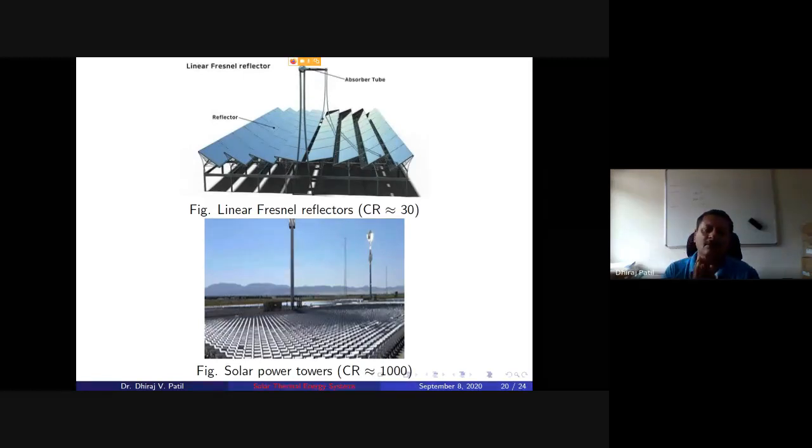So if I have 10 megawatt output at the shaft power, say after the generator, then you start calculating and find out what is the steam required, what is the capacity required, what is the turbine size, and what is the pressure, and all. You put your cycle on the Rankine plot, with realization, basically real cycles, and then you can back calculate how much energy you need, how much solar energy you need to concentrate to produce that much steam.